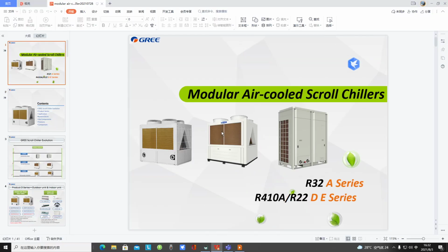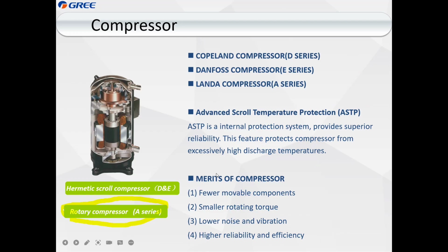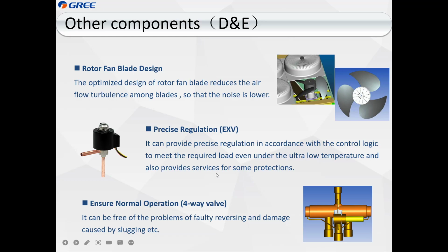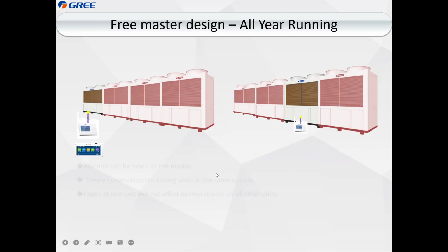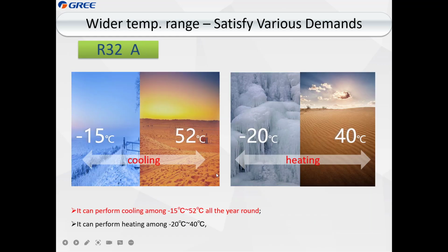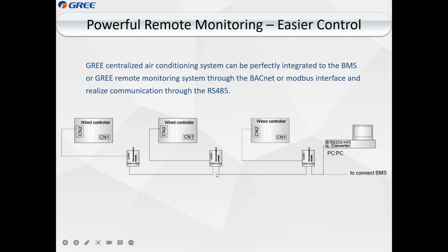In this slide, you said that with our compressor we have the lowest noise. Low noise means when we install the chiller into the building, the noise is very low. But can you show me the condition for testing the noise? For example, how many meters do we test the noise in front of the chiller? Because when we make a proposal for the customer, they will ask us what is the condition to test the noise.